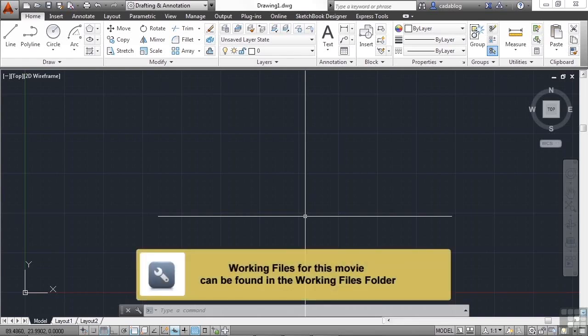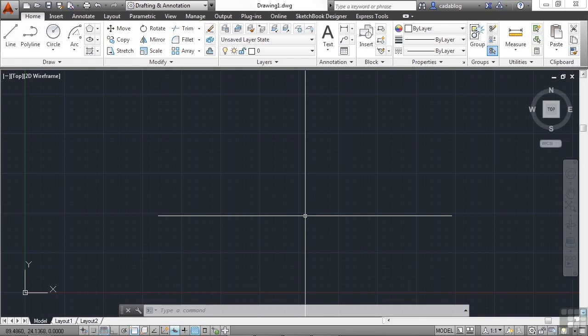Many times in your drawing, you will need lines to be a bit longer or a bit shorter. You'll also need your lines to butt up to other lines. That's where the trim and the extend commands come in. I've combined these two commands together because they're practically identical in function. The trim command will shorten your objects by cutting them away from different parts, and then the extend command will lengthen your lines to an extension line.